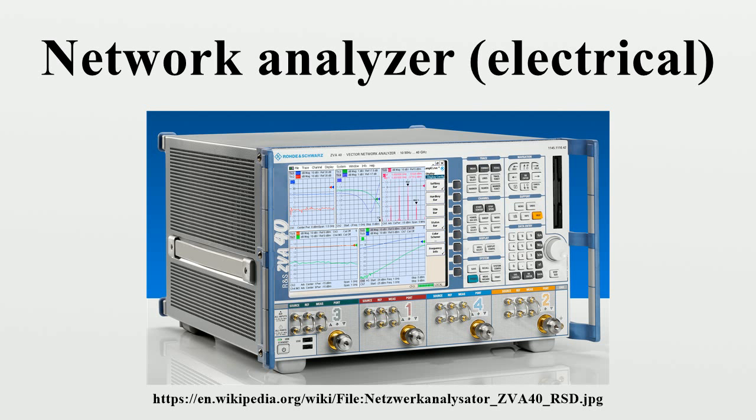The simplest calibration that can be performed on a network analyzer is a transmission measurement. This gives no phase information, and so gives similar data to a scalar network analyzer. The simplest calibration that can be performed on a network analyzer, whilst providing phase information, is a one-port calibration. This accounts for the 3 systematic errors which appear in one-port reflectivity measurements.